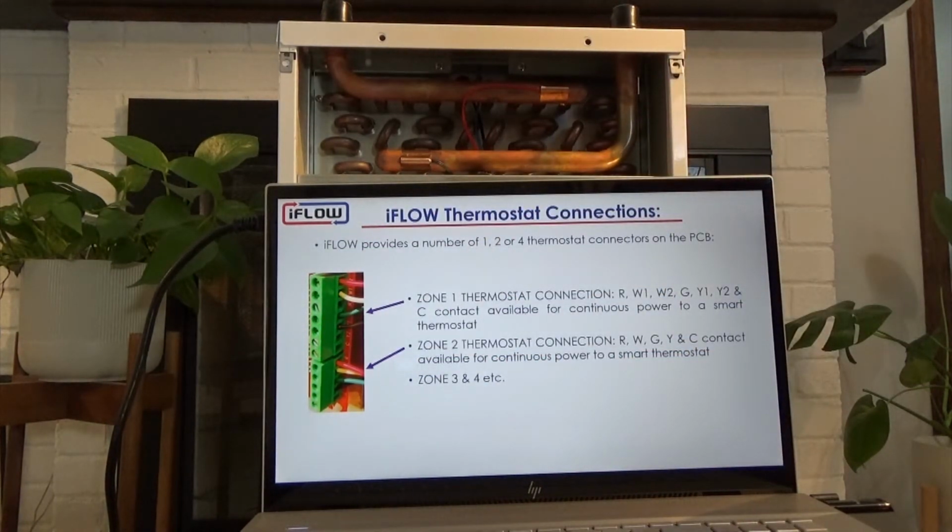Now, with regards to heat pump thermostats, on the heat pump thermostats, you can have emergency heat, that's usually an E. You have auxiliary. You can have O, B, coming directly from your thermostat in. We don't need any of that. Just turn your heat pump thermostat to conventional mode. Just run it with your 4 or 5 wires in. We will then decide, do we operate the heat pump or do we run the backup? So the iFLOW will decide, and it will send the signals accordingly. It does not need the thermostat to do that.